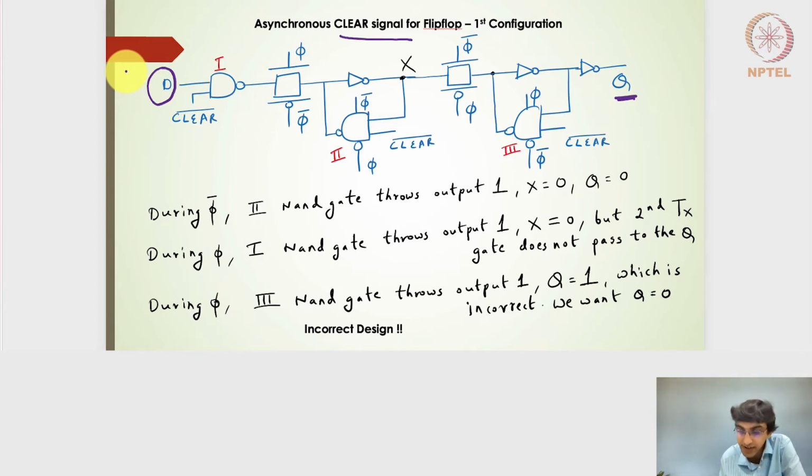In this particular design, the first latch is the positive level latch, and the second latch is the negative level latch. So this flip-flop design is considered to be a negative edge triggered flip-flop. With this understanding, what we really need is, if I press the clear signal during the high level or during the low level, I need Q to be 0, and Q should wait for the next negative edge, the falling edge of the clock, so as to get the updated D value.